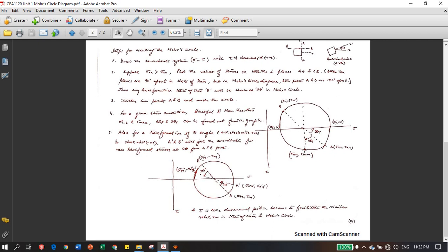The funny part, and the fact, is that the maximum value of shear stress will always be equal to the radius of the circle. And this point denotes sigma y because this is the center. The value of 2 theta s, the plane of maximum shear stress, is calculated from here, from the normal state of stress. This is how you can calculate by Mohr circle.